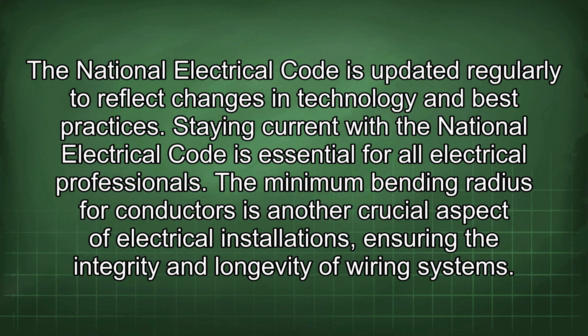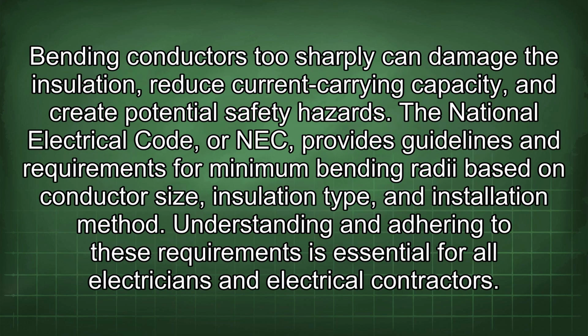The minimum bending radius for conductors is another crucial aspect of electrical installations, ensuring the integrity and longevity of wiring systems. Bending conductors too sharply can damage the insulation, reduce current carrying capacity, and create potential safety hazards.